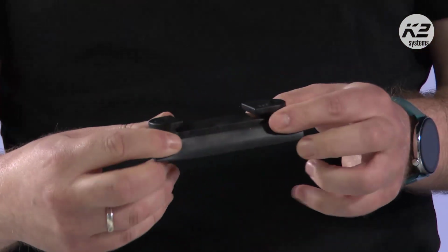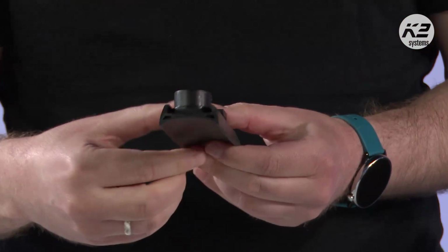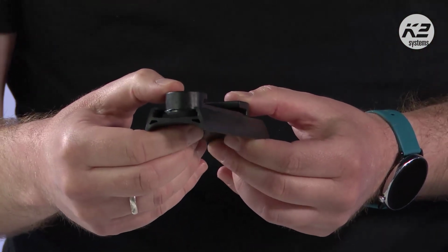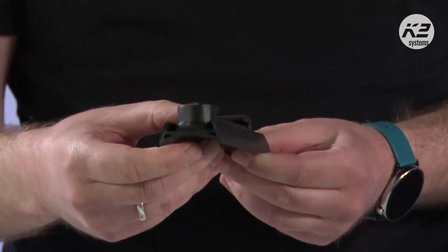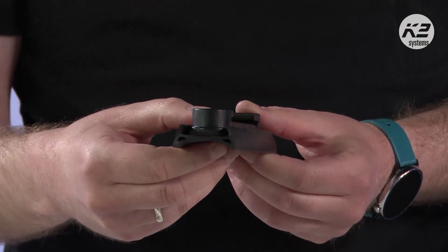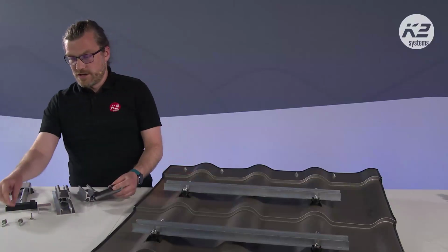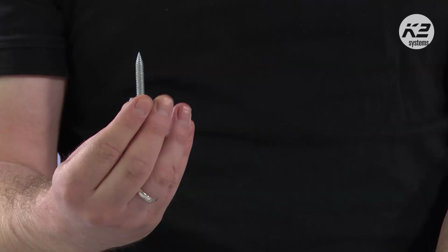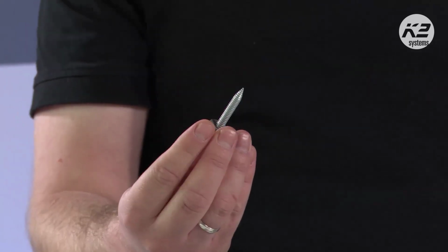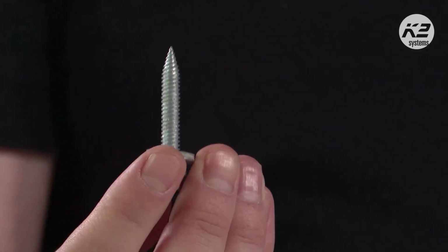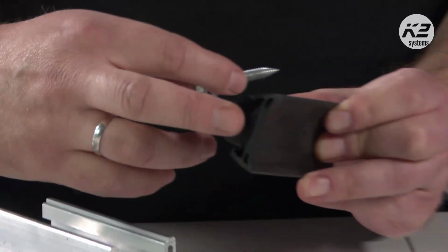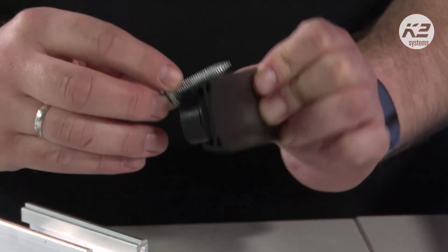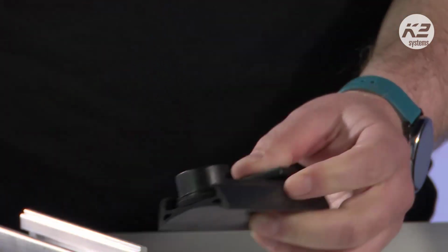And now you can install it on your curved metal sheet, preventing the water from going inside the roof covering. The screws are the same we use for our basic rails, for our basic clips, a bit longer than the screws we use for mini rail or multi rail because of this distance we have to go over. And then they are installed into the metal sheet.